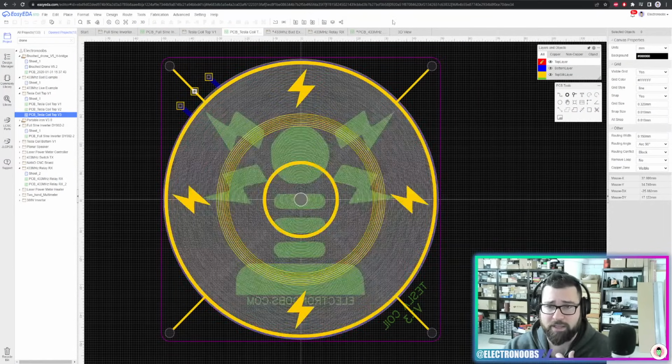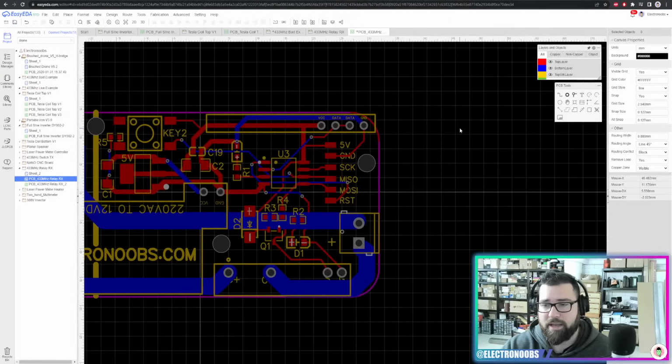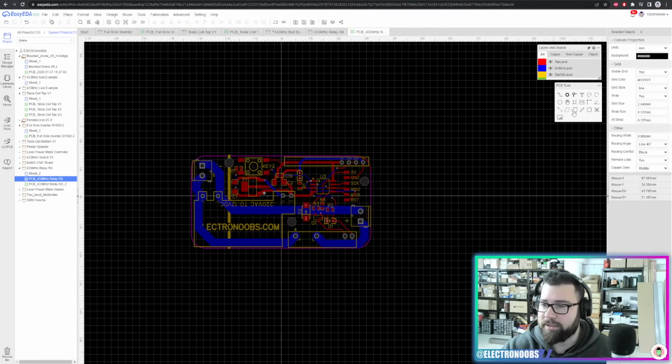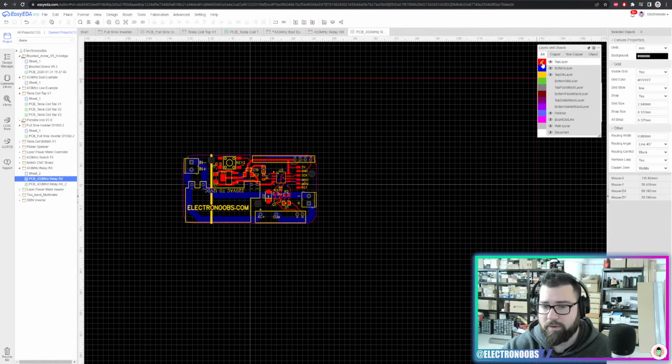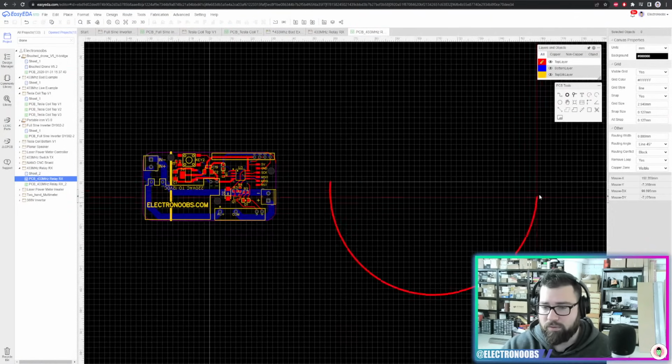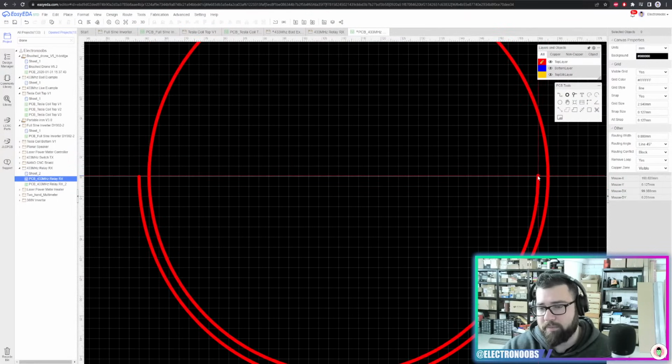If you want to make this, you just go to your PCB design, and instead of using a normal track, you click the circle one, which is this one here, arc center, and you place it here, then you go where you want the circle to end, you place another one here, then you start here and end here. That was made in spiral.